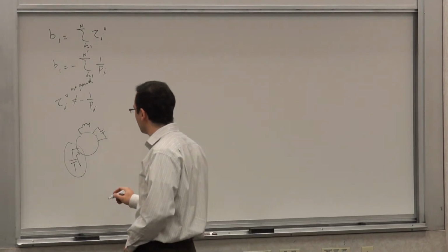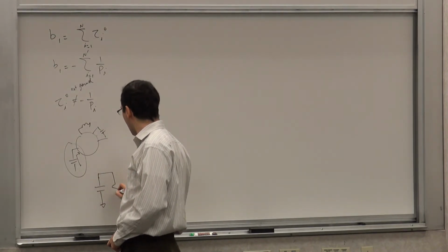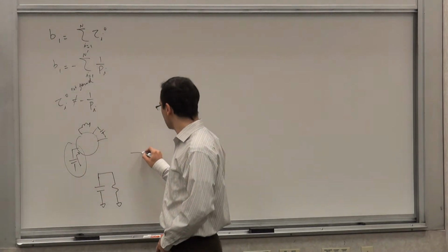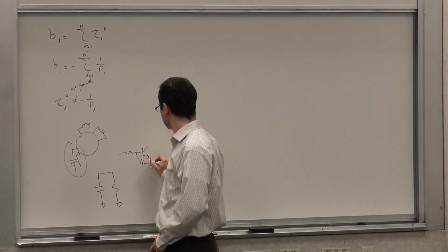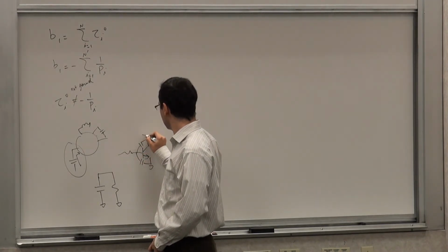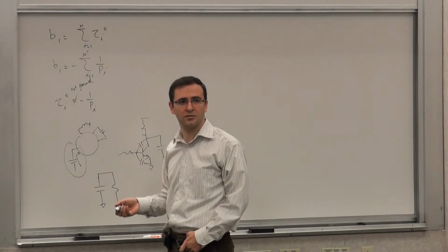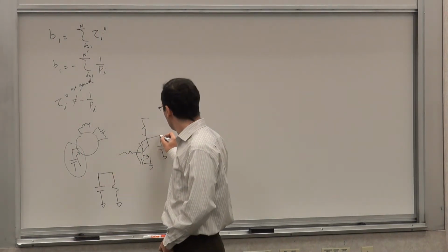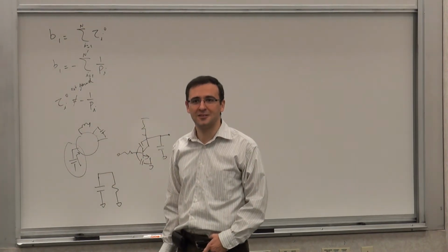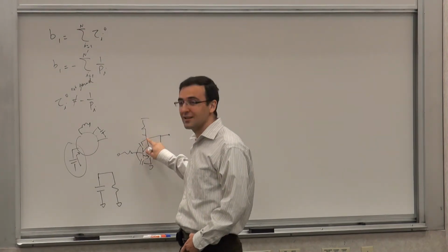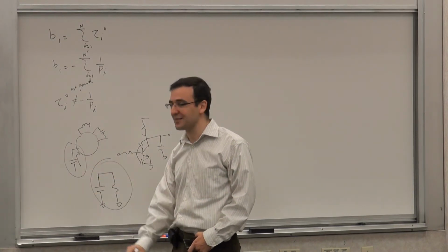An obvious and trivial example is this. Let's say you have a circuit. Let's say you have a common emitter, and then on the side you have this. That has nothing to do with your common emitter. Again, this is a trivial example, but we had non-trivial examples. A common base was a non-trivial example. Two time constants are uncoupled. But if you have something like this, and this is sitting there by itself, no matter what you do to these other guys, the resistance seen by this guy is the same, right? So this represents an independent pole.